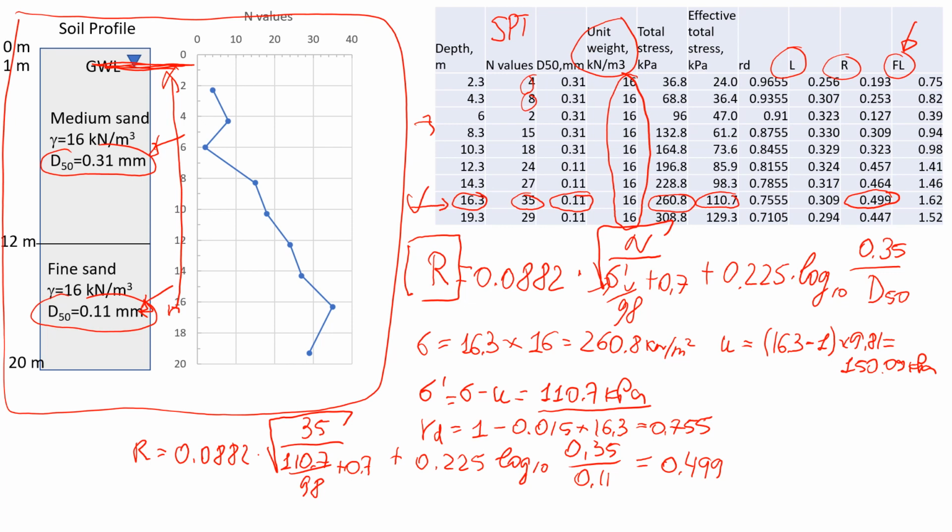Okay, so now let's get the value of L for the same depth. As already mentioned, or maybe I didn't mention it, the earthquake that we're going to design against is going to have a maximum acceleration of 170 gals. So you can go back to the previous slide and see it written at the bottom. So we're going to divide by the g. In this case, it's 980.